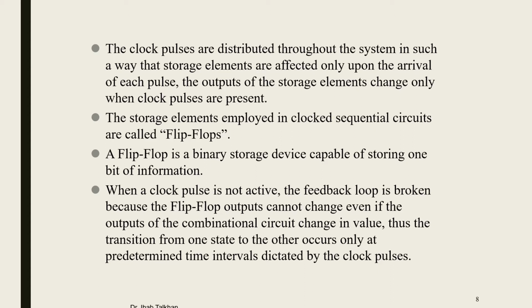And that's why it says here, when the clock is not active, even if you have the combinational circuit, it will not work unless the storage element gives the order for the next state to change to present state, because the output is a function of inputs and present state, and the next state is a function of inputs and present state. This is the dependency, and this explains what is written here, and I'm going to show you by graphics in the next slide.